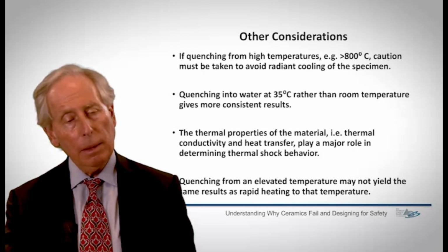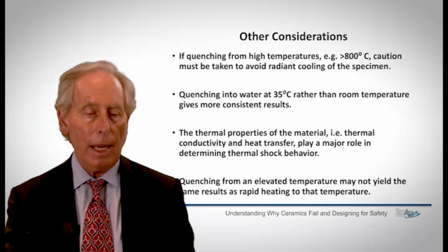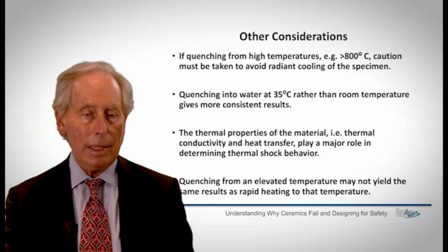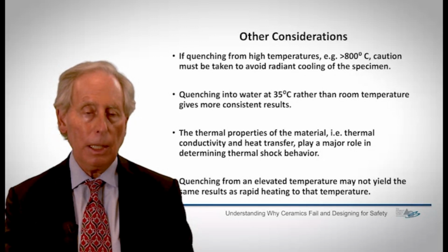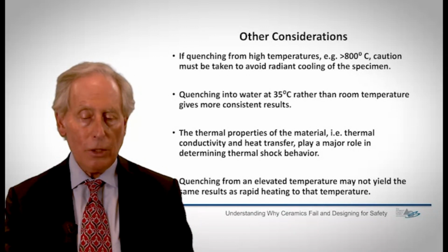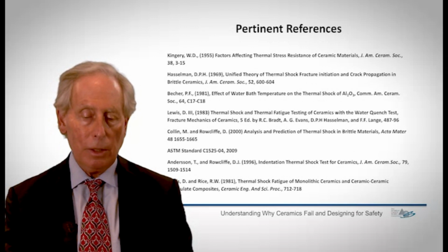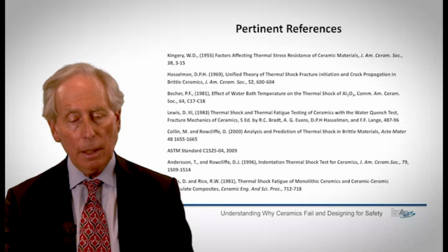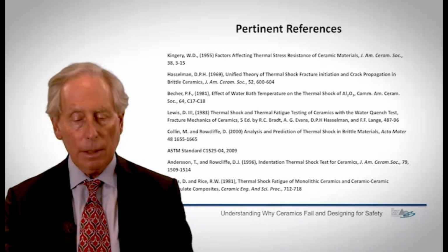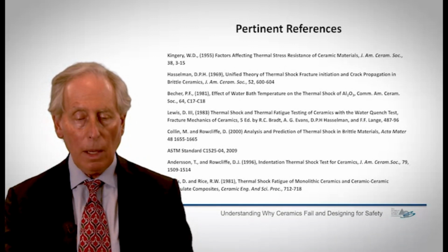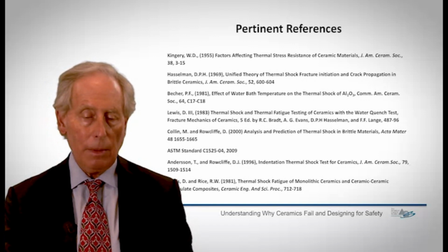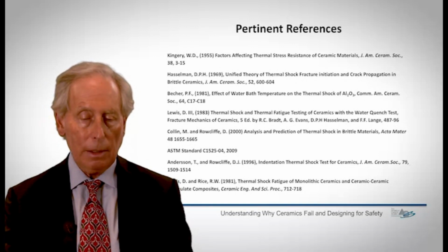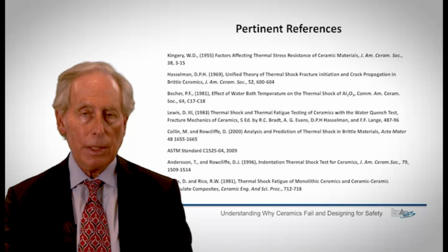So when we talk about applications such as gas turbines, I can get thermal stresses developed during heating up a gas turbine blade, for example, but quenching that same blade from elevated temperature may not give me the right information as to what might happen in heating. So there's a lot more detail than I can give in this length of time, but I thought it worthwhile pointing out some of the basics about thermal shock testing and giving a few pertinent references to this topic.